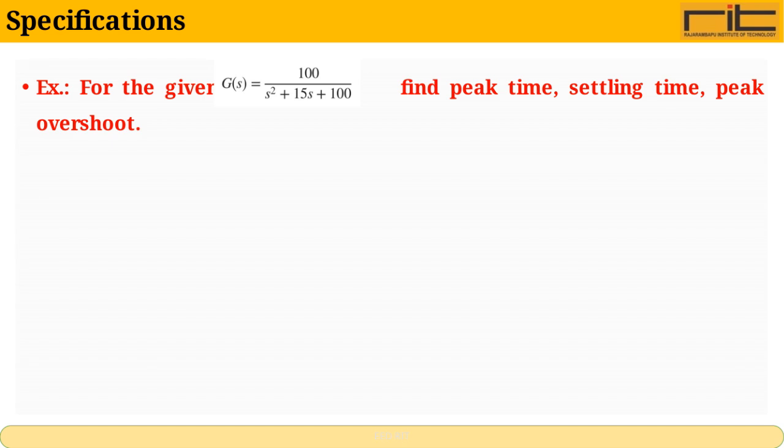Lastly, the settling time, denoted as Ts, is the time required for the system to remain within a certain percentage band around the final value, which is 0.533 seconds for this example. Understanding these specifications helps in designing and tuning control systems to achieve desired performance and stability.